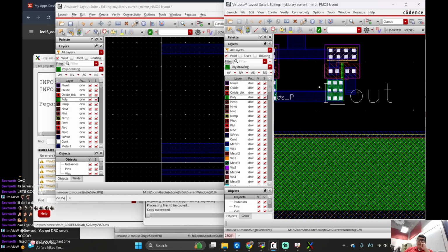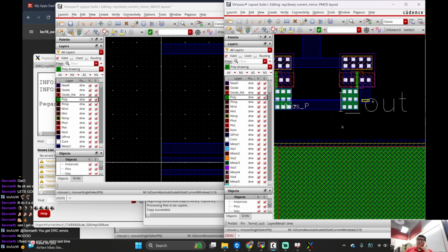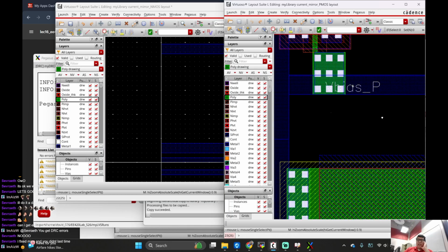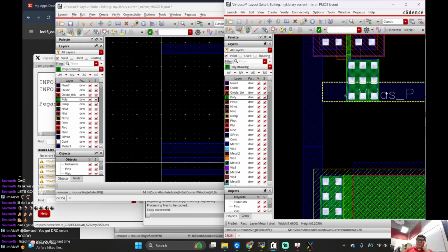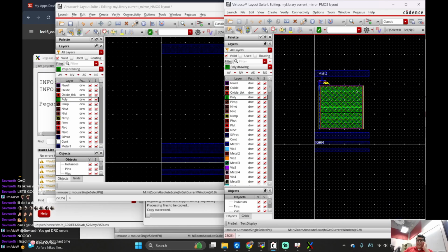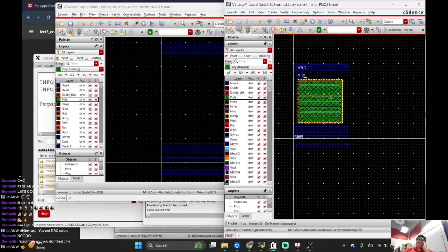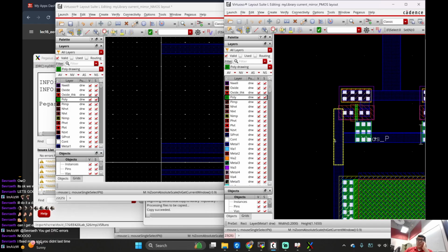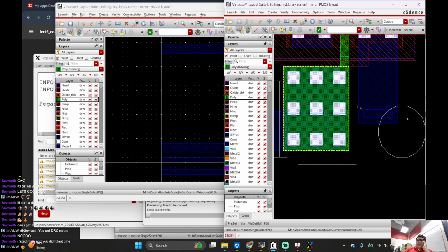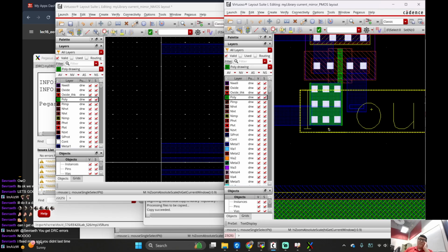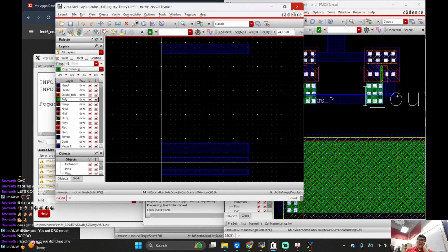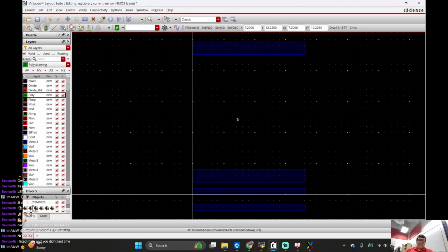And you know how I did the ×1 and the ×5 PMOSs? What I'm claiming is that if I copy pasted this circuit and the ×5 together, this voltage should be the same for both circuits. Because this is the one that's floating. This one doesn't see V bias P. V bias P is buffered by this guy right here. I'll show you an example, because now I actually want to see it.